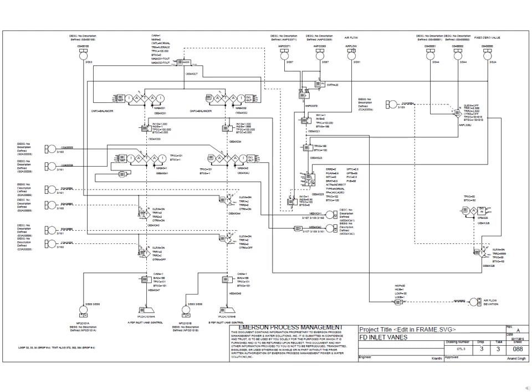Okay, we have the analog inputs at the top, analog outputs at the bottom. Another dilemma is that most of the inputs or outputs are not labeled. So you have to trace where it came from for you to have an idea of what it is. But those who are familiar with control sheets know right away just by looking at the title or sheet number. Digital inputs on the left, PID controller, several transfer blocks and manual stations.